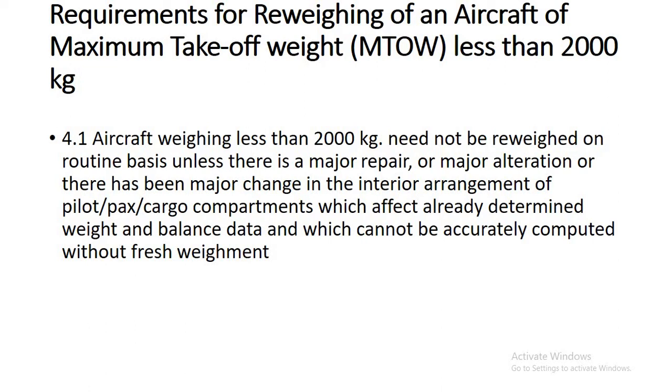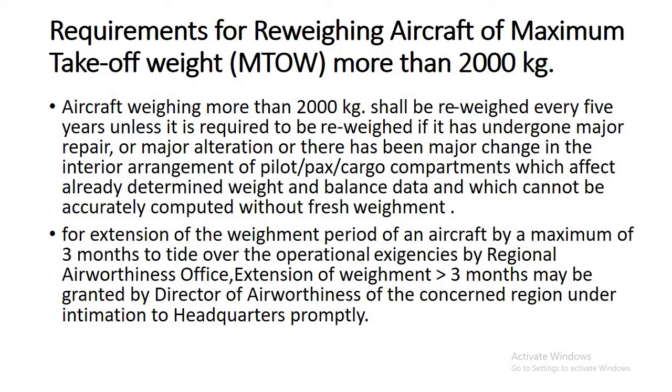Okay, that's one condition. What if your aircraft's maximum takeoff weight is greater than 2000? Then every 5 years you have to reweigh the aircraft. Okay, that is the normal condition.